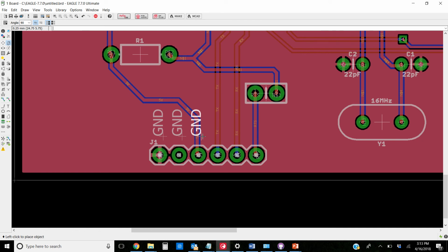move that over. Now you can put this over traces. You can also write it over vias, but depending on how you did the via, and in our case how we did the via, all of these green dots, if you were to put it over like this, you wouldn't see most of it. Anywhere that green is or those black spaces, it would all be wiped out. You would just see a little bit of the G and a little bit of the D. So that's not going to be an acceptable way to do this. You would need to put it to the side.